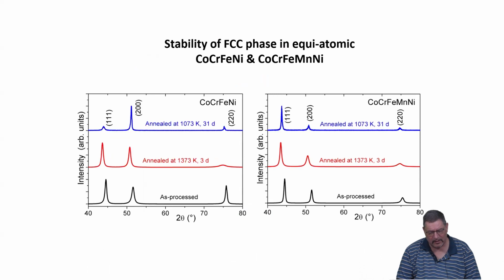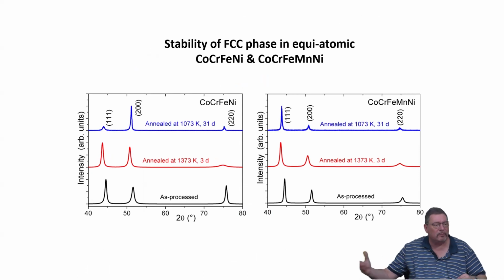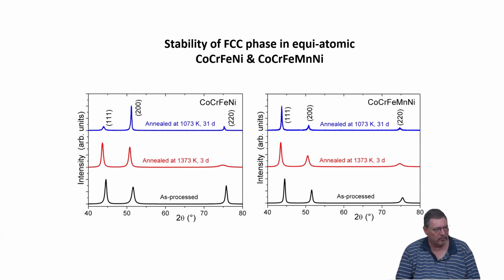Yeah, so then going from volume diffusion in a system which doesn't have grain boundaries, we are now obviously interested in the real material. The real material would not be an artificial single crystal, but polycrystalline material obtained after some casting process or arc melting process or so. But in order now to analyze, is diffusion sluggish or not, we have to have a comparison, right?